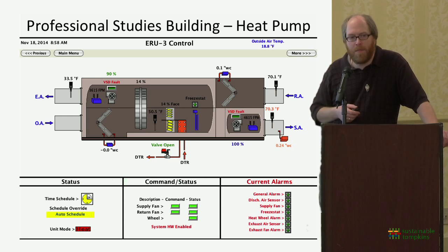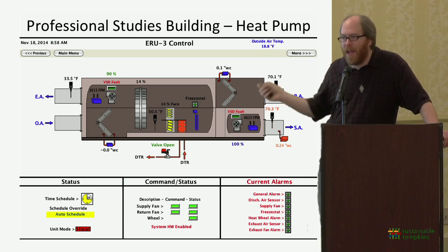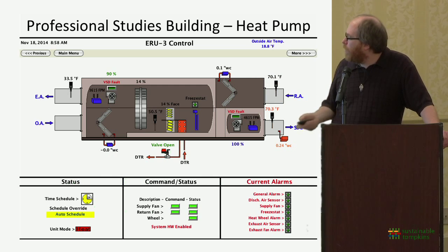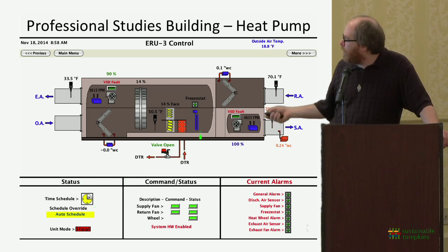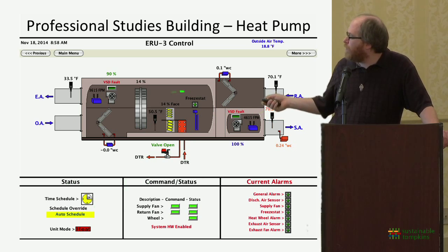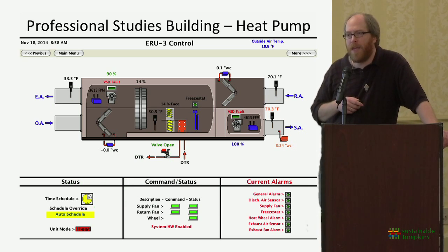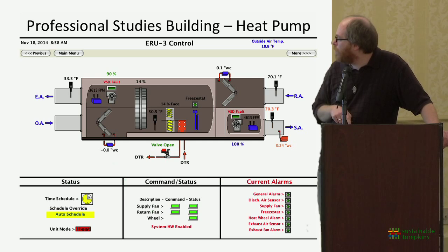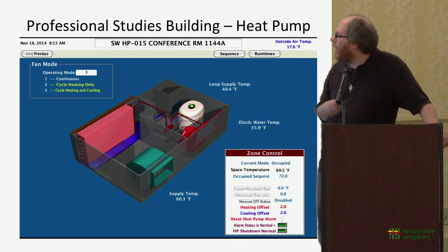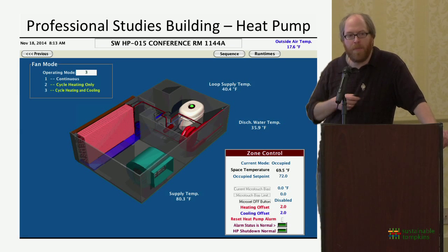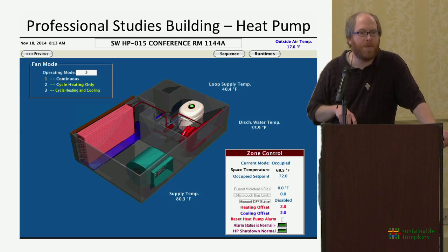We use the system in its more complex way. So we have an energy recovery unit on the top that's fed by the heat pump system. Outside air is brought in and preheated, both by the existing air that's on the way out and by the heat pumps, big heat pump units. We have 3 large ones. But we also have 180 small heat pumps distributed throughout the building, and this is where you can optimize heat flow.